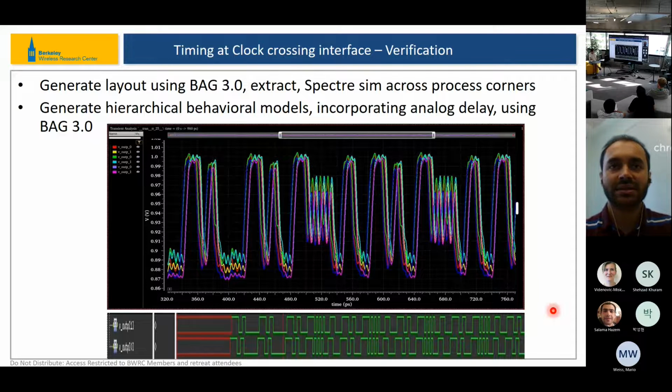The way he learned it was a mix of reading through some code, some documentation, and trying out some simple examples. So you look at the inverter example. Another example that I think is very useful for making new users familiar with the programmability is to take a circuit implemented in NMOS, like a StrongARM with NMOS input, and include some programmability in the generator so that it can generate a PMOS input StrongARM without writing a new generator. You just add a flag so that you can say whether you want an NMOS input or a PMOS input. By doing small examples, you start to learn it.